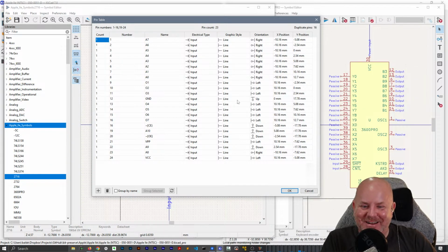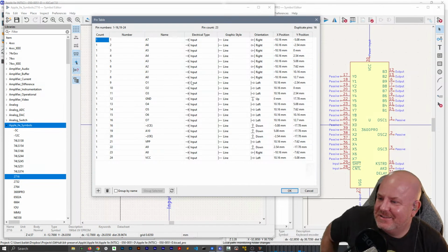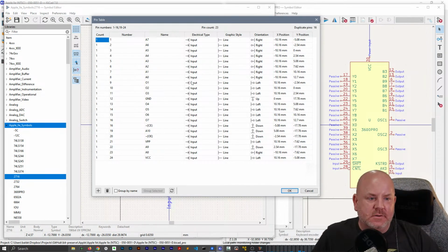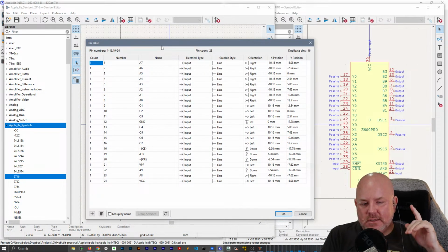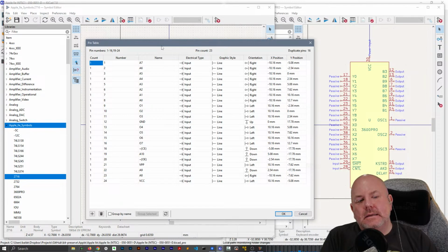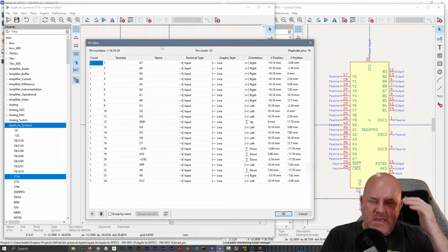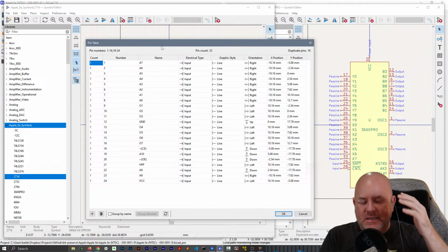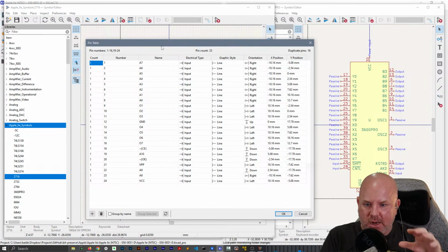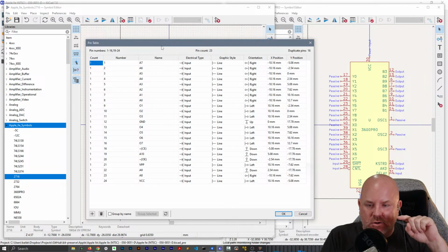Bipolar on the high side, FETs on the bottom. Yeah. You know, the pins aren't in order. Oh, actually, that doesn't matter at all. For the most part, it doesn't actually matter because they're just address pins for the EEPROM. As long as its bits line up with what's in the EEPROM, or I keep saying EEPROM, it's not an EEPROM, it's a masked ROM, so the ROM chip. It's actually pretty common that your address lines don't line up in order.